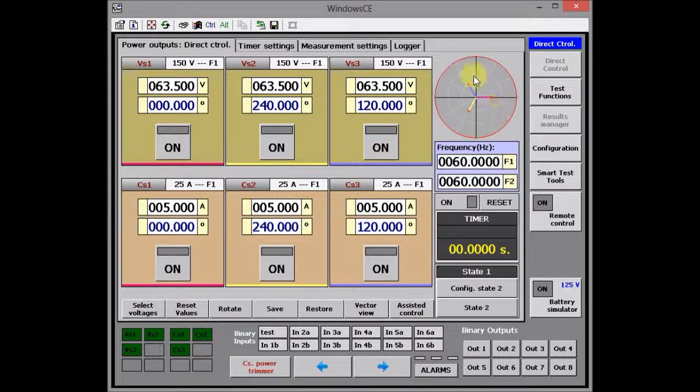The values viewer. Any situation that is created in terms of voltage, currents, and phase angles in the main control screen can be seen from now on in terms of the different electrical parameters that are more frequently used in relay testing. By default, there is the vector representation, which is one of the ways to see the adjusted values. By clicking on it, we start the sequence of views available. The first one is the sequences, seeing all the values in terms of zero, positive, and negative sequence.